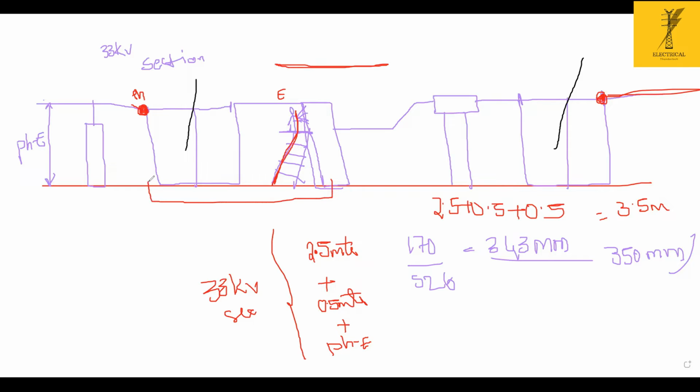That is the one case. The other case is that some breakers will fail. When the breaker fails and explodes, it should not damage the other adjacent equipment. So based on these two factors, we maintain the distance between these equipments. That is the reason for the sectional clearances, and from a safety point of view, we maintain a distance from this breaker towards the adjacent breakers, and from equipment to equipment. That is the point.